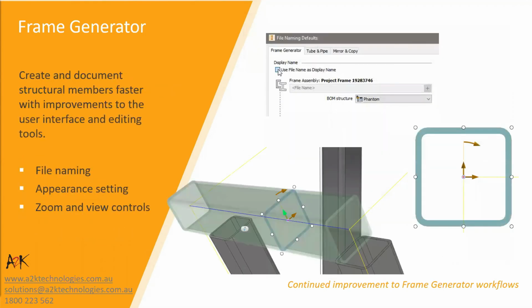Now the insert command now previews the member shape and displays an origin glyph when you highlight the sketch geometry. If you move your cursor along the placement sketch, you can change the location of the origin and profile before you click. There are new display controls in the property panel that set the zoom and view orientation.